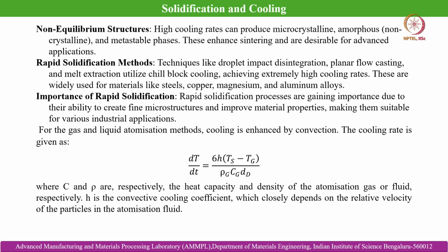So what is the importance of rapid solidification? Rapid solidification processes are gaining importance due to their ability to create very fine microstructures and improved material properties, making them suitable for various industrial applications. For the gas and liquid atomization techniques, cooling is enhanced by convection.